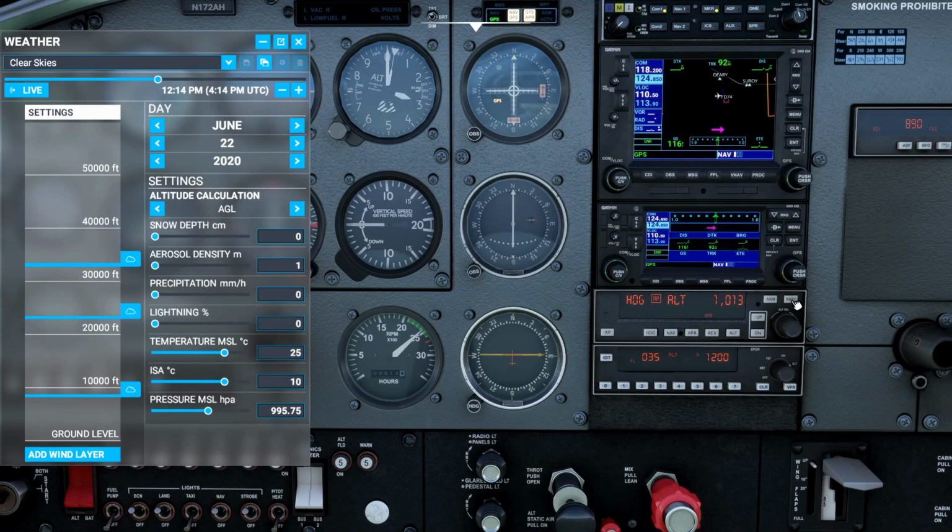So it does not capture that correctly. And there is a BARO function in here. You press the BARO and it brings up the altimeter setting, and I can roll it down, it takes a little while, to 995, but it doesn't make any corrections. So this does not function, and it doesn't correct that because it should be correcting back to 3,500 feet now, but it's still just holding that pressure altitude.